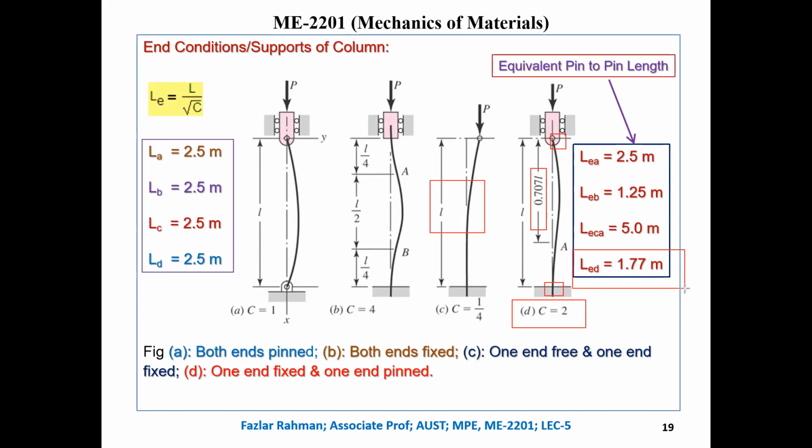I'm giving you a 5 feet column, both ends fixed. So you're making a house in your building. But instead of fixed to fixed, if you use pin to pin, but you want to carry the same load, then what will happen? You need to make the column shorter. Okay, that is the criteria of equivalent length. And why are you doing this? Because we apply the Euler equation in all end conditions. That's why we figure out the equivalent length of the column.